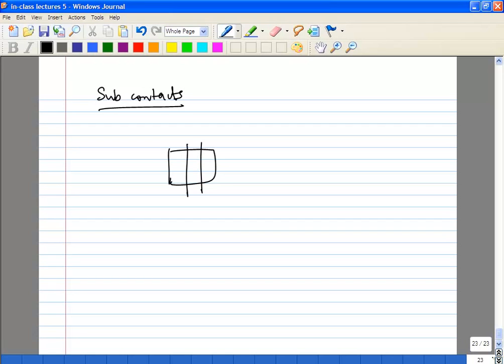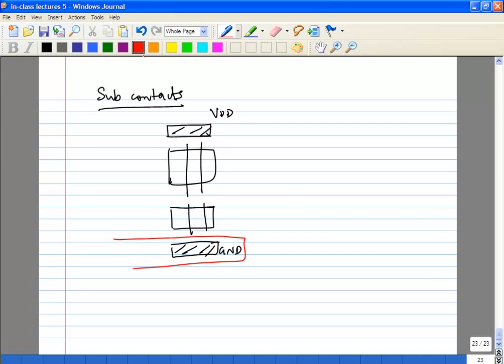So let's just take the case of a transistor. Let's take an inverter, maybe that's the easiest, with 2 fingers. Normally, this is your VDD and ground, and you would put your substrate contacts right below your VDD and ground lines. It would look like this. But if your circuit is sensitive, you may also want to put in contacts here on the sides.